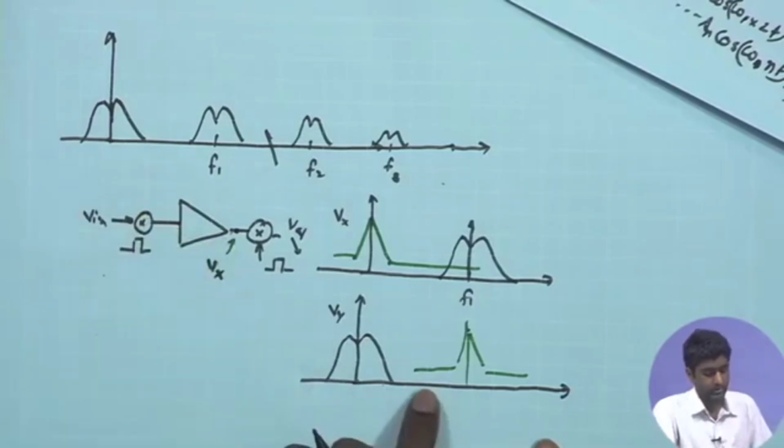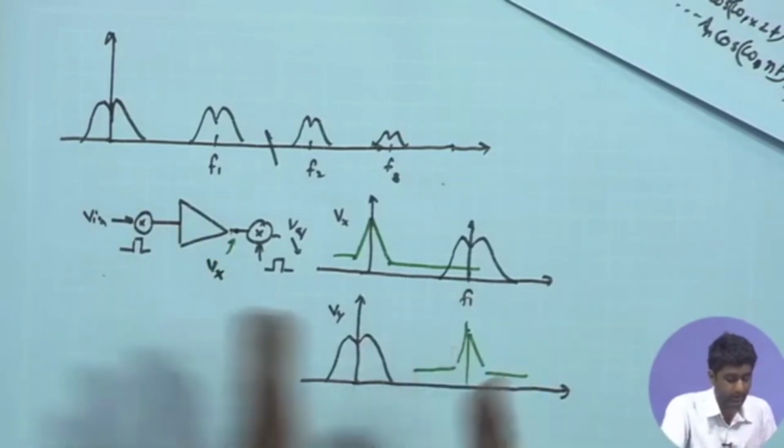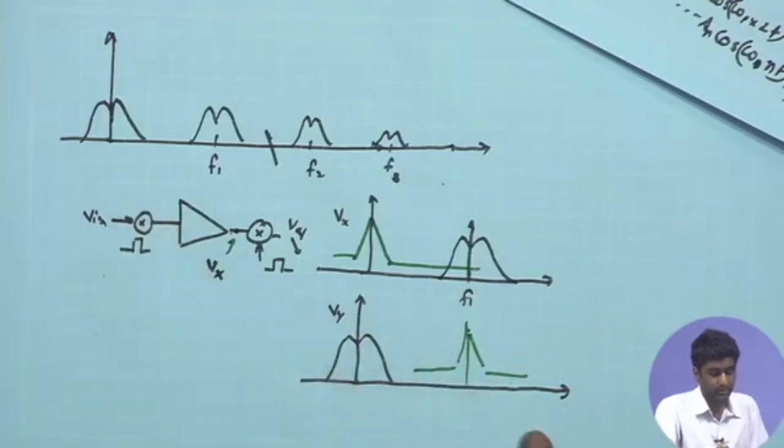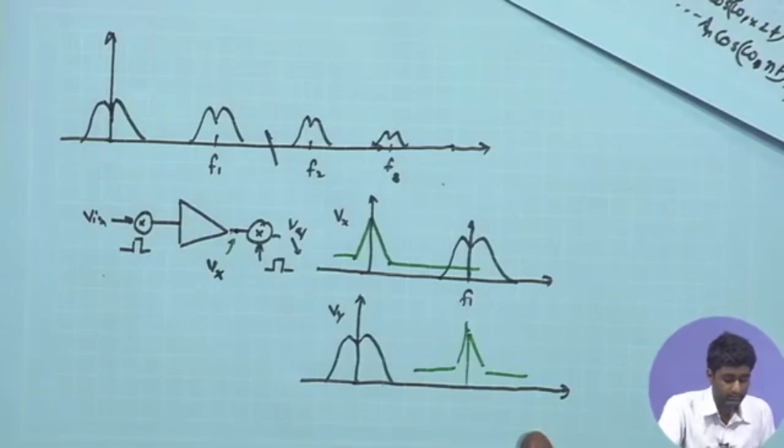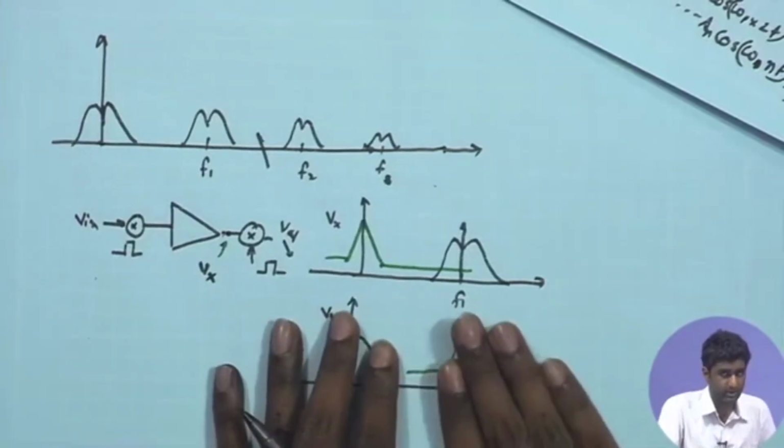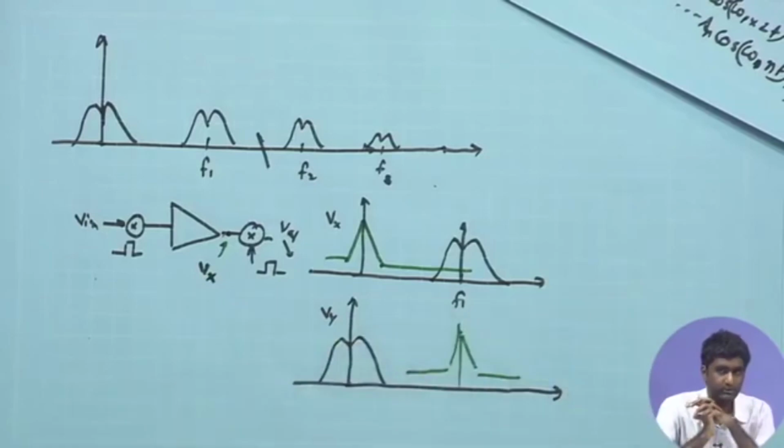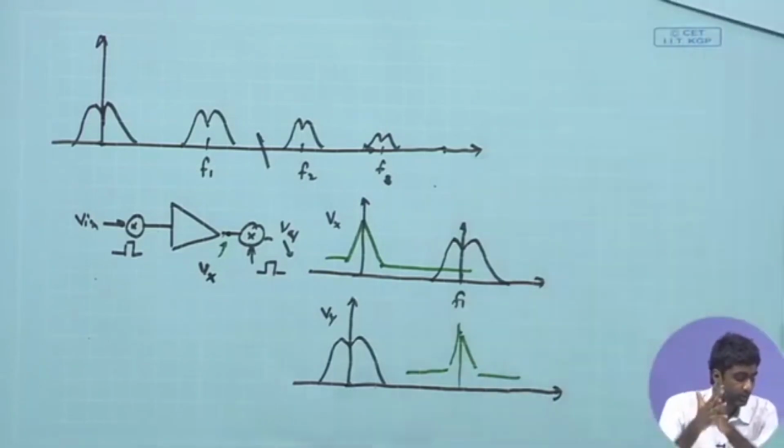So, this is one of the ways in which we can mitigate the effect of 1/f noise. Now, this is the ideal picture. There are of course some issues related with this 1/f noise cancellation and chopping as well, and that is going to help us in determining how to choose the chopping frequencies, and what the trade-offs are in choosing the chopping frequencies appropriately. So, let us first look at the choice of chopping frequency.